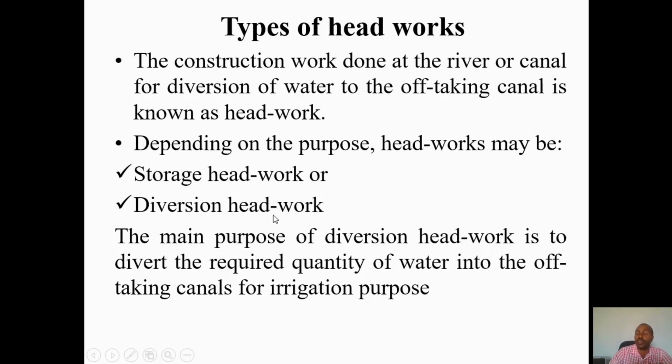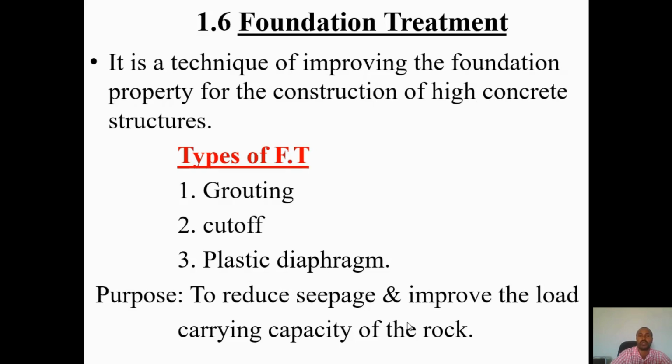Storage headwork or diversion headwork, depending upon purpose, you may provide storage headwork or diversion headwork. Directly it will be diverted, otherwise storing water, then you can use. So the main purpose of diversion headwork is to divert the required quantity of water into the off-taking canal for irrigation purpose or for water supply purpose or other purpose. You can take out water from diversion headwork.